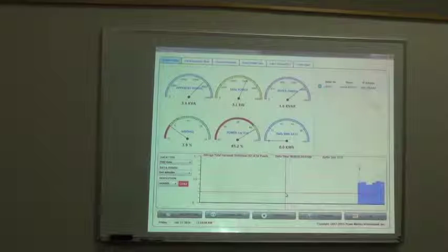If it goes up, in other words, if it's creating resonance, then I shut it off. If the resonance is so much that the harmonic doubled, the true resonance, I physically shut all the banks off and we restart the reevaluation. If I just saw it went up by a certain percentage, I'm not sure if it's 10 or 15%, I have to look it up, then I basically just go back to the previous value of the capacitance. You know what I'm saying?